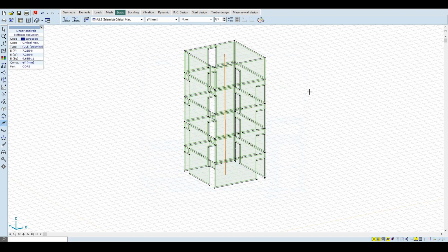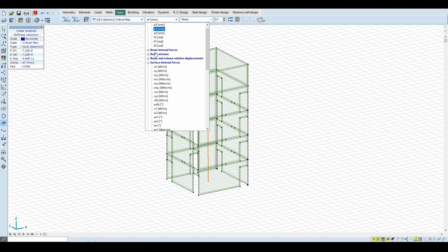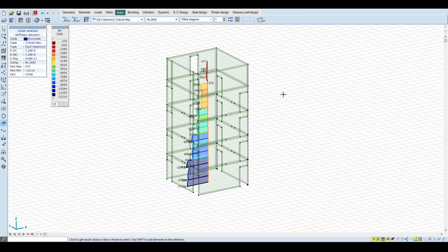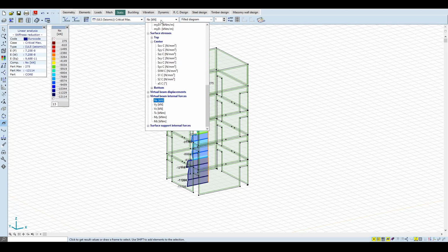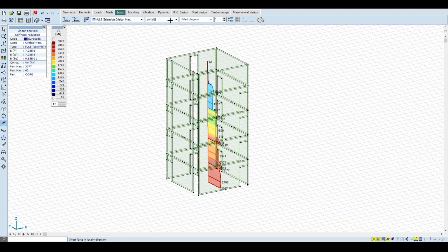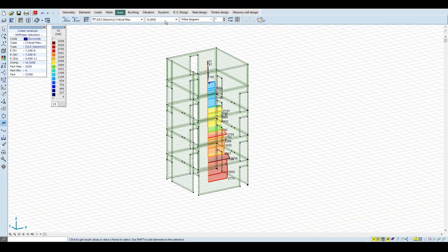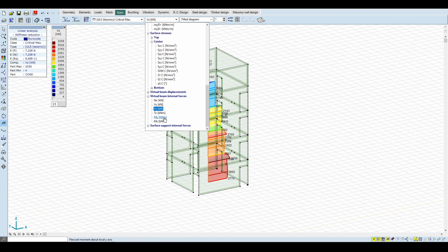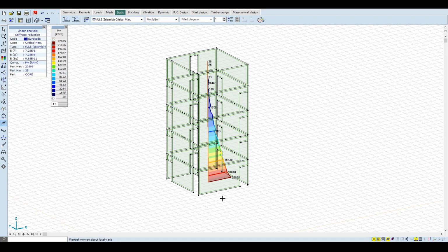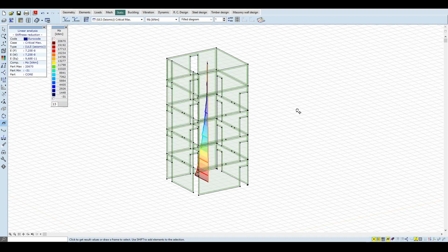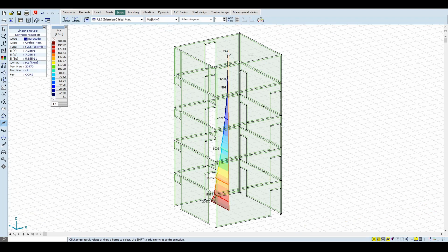We can check the global normal force of the core, which comes from the considered mass in the seismic combination. We can also check the integrated base shear forces, which are basically the total horizontal force acting on the building, since the columns have hinged ends. And also, we can display the global bending moments, which are useful for the assessment of the global behavior and for the estimation of the required wall thickness in a preliminary design phase.